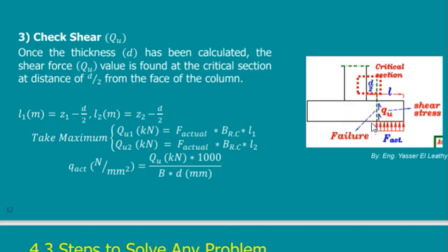Beyond it, you will be affected by the effect of the column, because the column has some load, and this load is pushing the foundation down. It starts from this point and goes down like this with an angle. So it is preventing you from shearing anything below it.